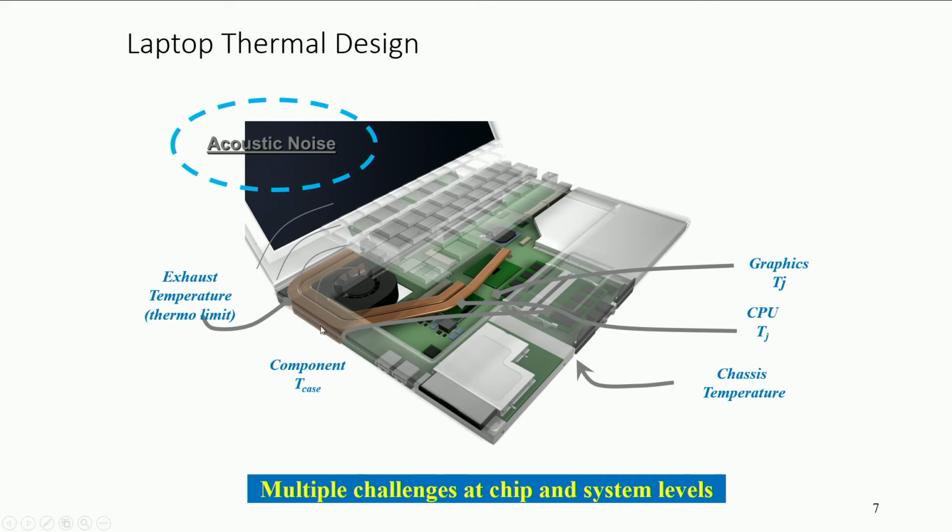The exhaust limit, because remember this temperature that is being drawn in is at ambient temperature. As it flows over all these components, it is picking up heat, it is getting heated up. Then finally it comes to the fan over here. Okay, and finally it comes to this heat exchanger where it picks up the heat from the CPU as well, and in this case CPU plus graphics, and it comes out. Clear? So this exhaust temperature is much hotter compared to ambient.